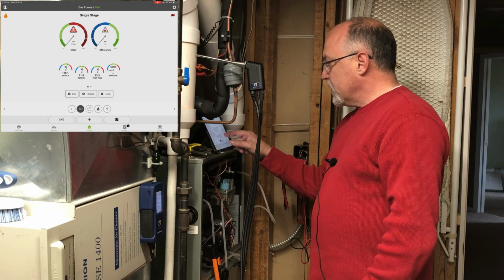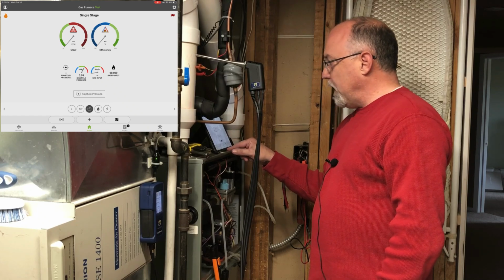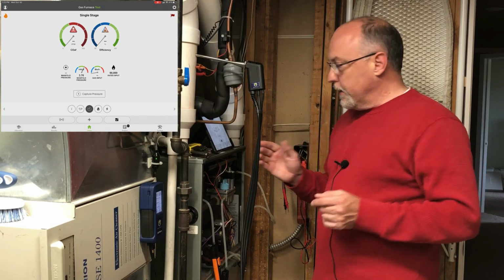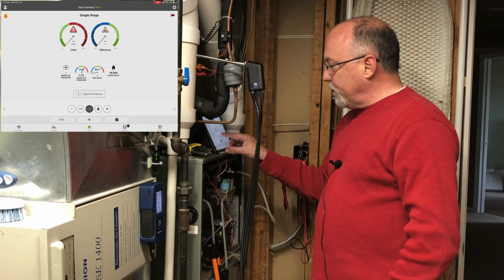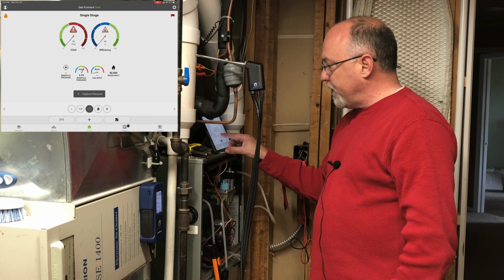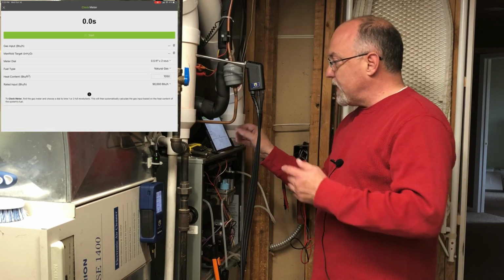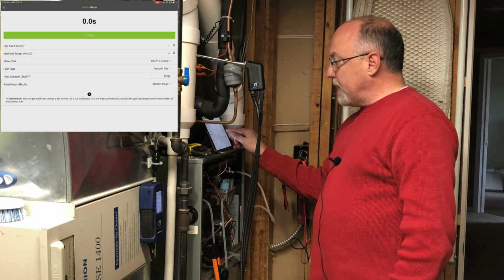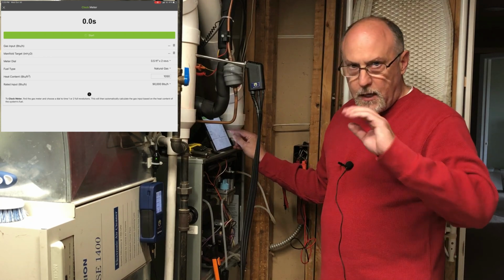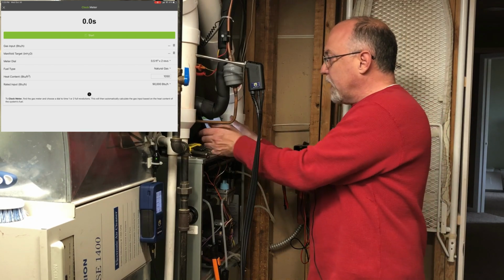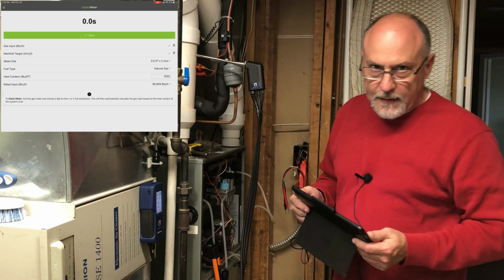All right. So let's go in here to capture the pressure. Now, this is when we get a lot of questions on how do you use this feature on the meter. So the first thing I'm going to do is capture the pressure. It's currently at 3.75 inches. And now I'm going to go ahead and clock the meter. So we're going to go outside here. Notice my heat content is in at 1050 BTUs. I already profiled this, so I have 90,000 BTUs here. We're going to go outside, we're going to clock the meter, we'll make sure the input's correct. So I'll be right back.